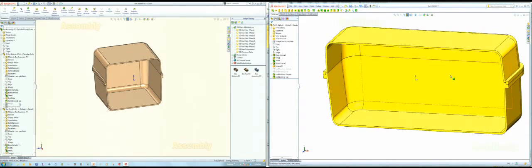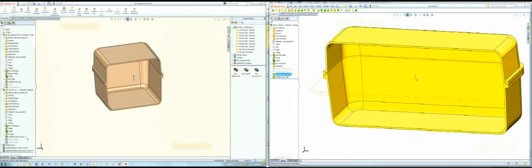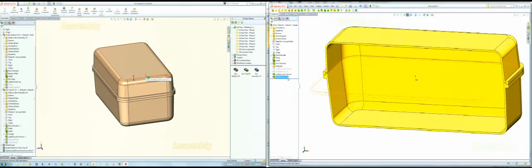If you look at the lip and groove feature, here's the lip and groove feature in the bottom. It's just a standalone feature. But if you go to the box top, there's an external reference. This is going to come into play later when we start trying to break all these in-context relationships. So the feature really belongs in the bottom part, but it's linked to the top. That's one thing I neglected to mention. If you notice on my feature tree, there are two features, and it splits them up, but they're tied intimately together.